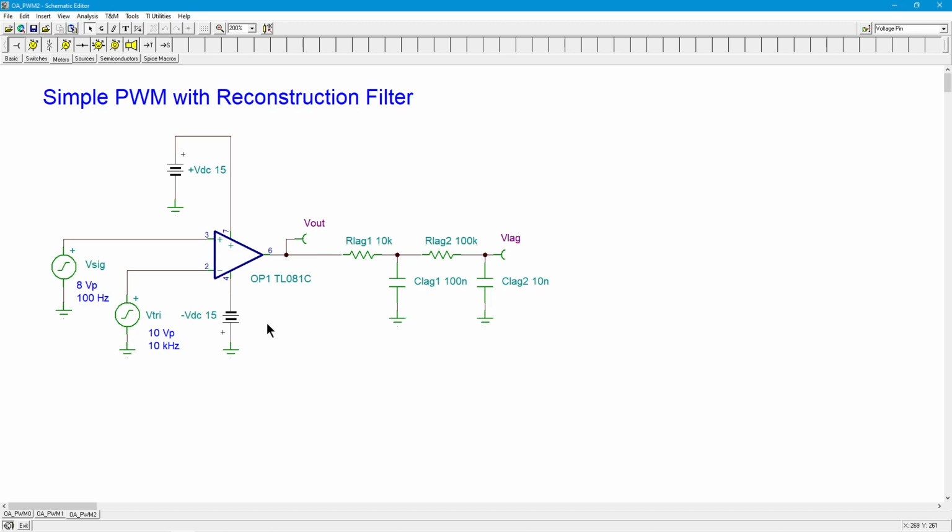Otherwise, all those high frequencies coming in from the square pulses are going to go into the voice coil of the loudspeaker, and they're going to do nothing but create distortion and heat, which is not something you want. But the important thing is we can see that the information is, in fact, encoded in those pulses in the form of a varying width. Hence, pulse width modulation. Ta-da!